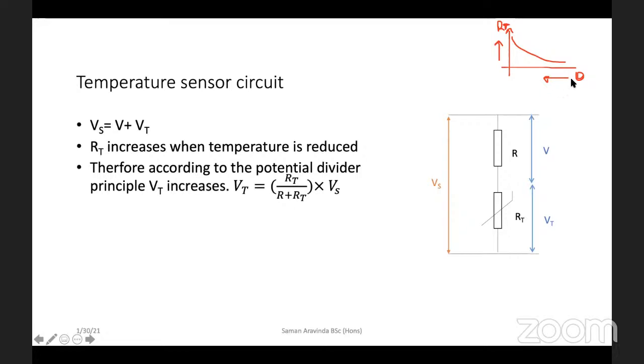Now, as the temperature cools down, what happens? Resistance increases. When the resistance increases, what happens to that potential difference? It also increases. So at 5 volts, what happens? If I have connected the heating mechanism across the thermistor, it will trigger and turn on. Am I clear?